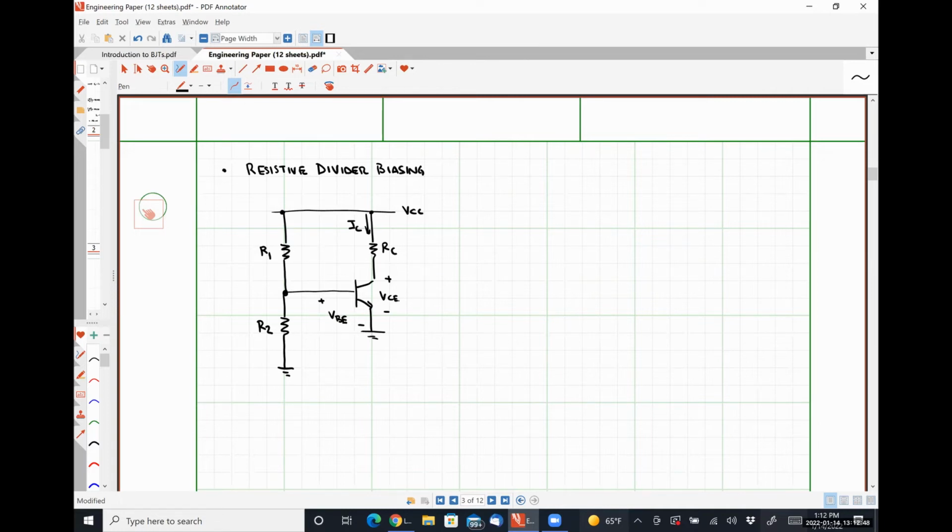This guy ain't linear. Okay. Our BJT, by definition, in large signal operation, is not linear. But these two little resistors over here are. Okay. So I don't have to include the whole thing in my Thevenin equivalent. I can just look at a part that is linear and get the equivalent of that and see what falls out.